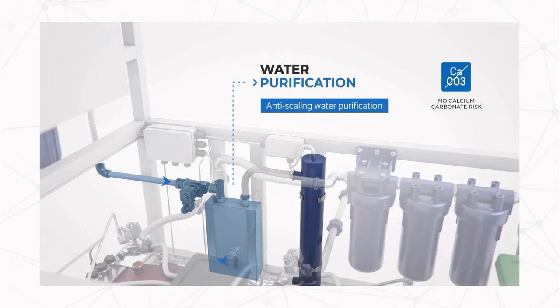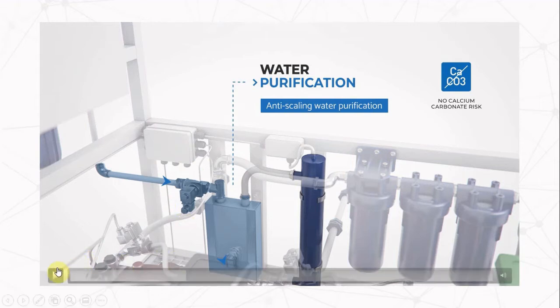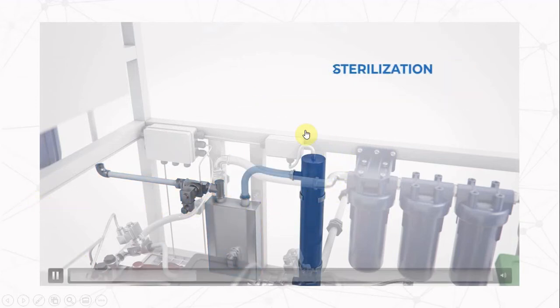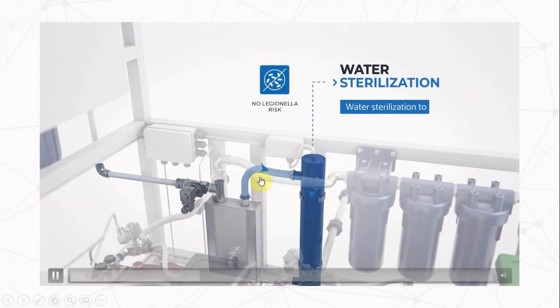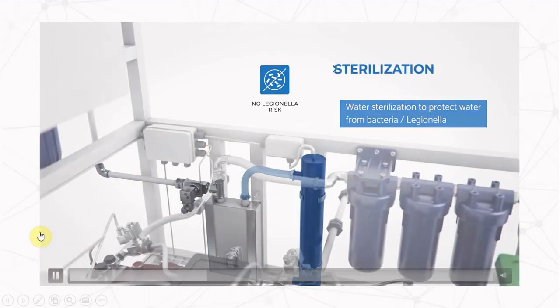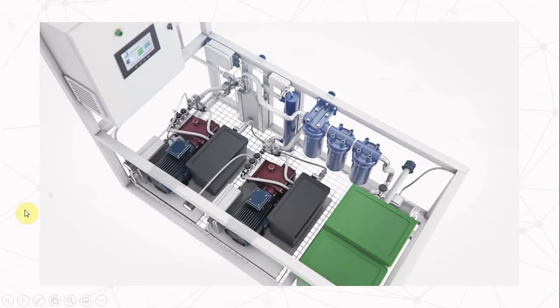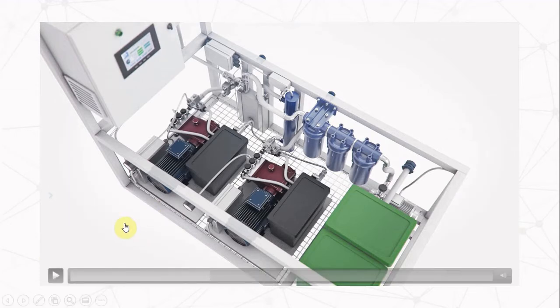Once the water is treated against limescale, it is very important to treat the water against Legionella bacteria. This task is performed by the device's ultraviolet lamp, which is adjusted for just the right amount of water passing around the lamp. This method to prevent the growth of Legionella bacteria is approved by all governments around the world and complies with regulations on how to exterminate Legionella bacteria.